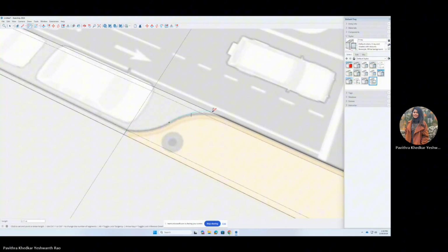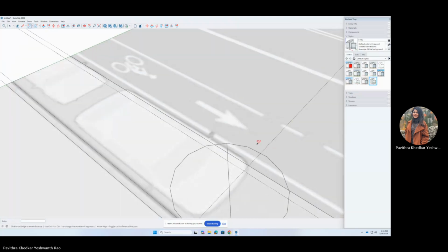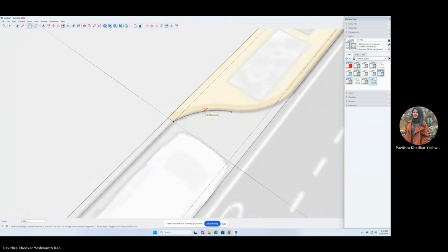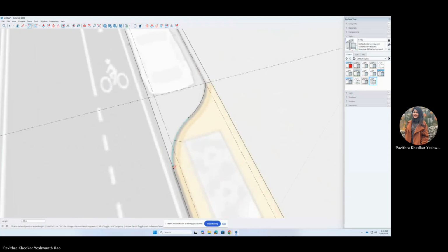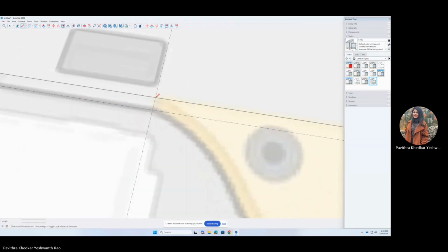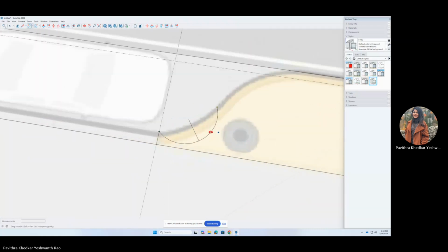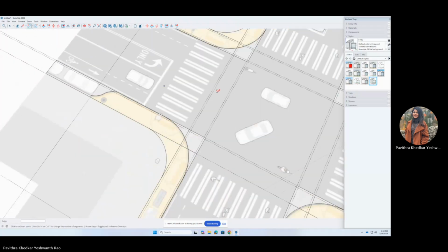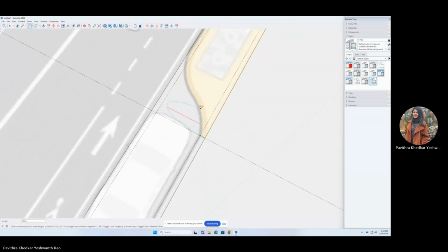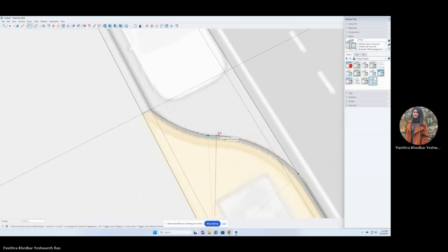Tracing and organizing geometry in SketchUp. Once guidelines are set, use drawing tools like the line, rectangle, circle, and arc to trace the entire reference image accurately. Adjust the style settings in the style menu to ensure visibility of the reference image beneath the surface you create. Delete unwanted lines to maintain clean geometry, preventing unnecessary edges or fragmented surfaces.